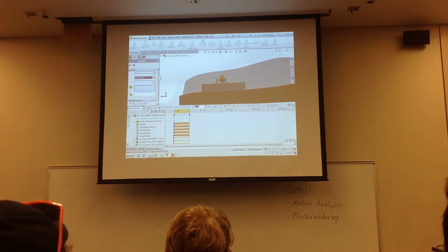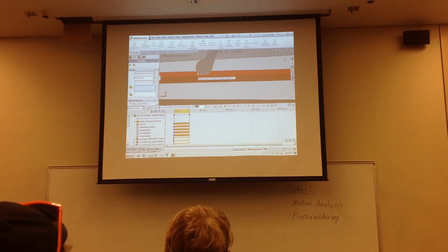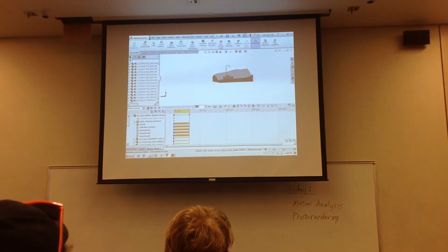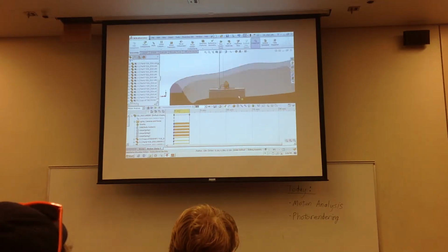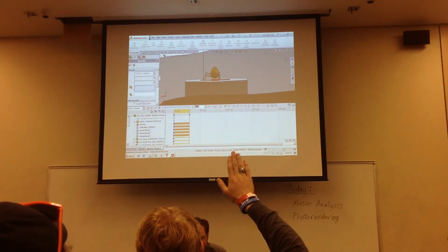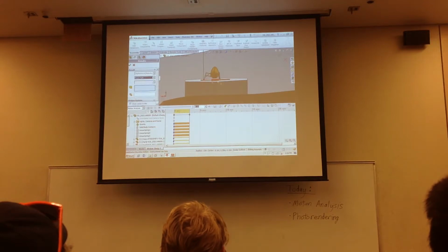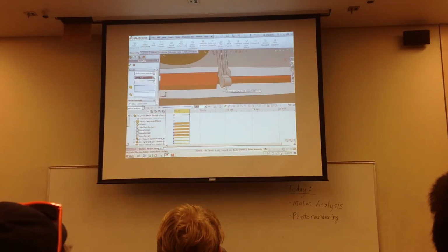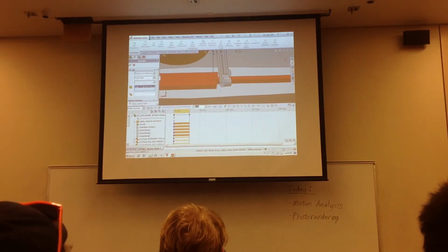And what that's going to do, if I click on some feature, like say the edge of this foot, if I select that, say OK, what that does is simply draw a line that follows the path that that feature took. Because it's not a single point, it's taking like the average of the curve of the radius. I believe what it does is find the center point. So it's tracing the path of that center point.